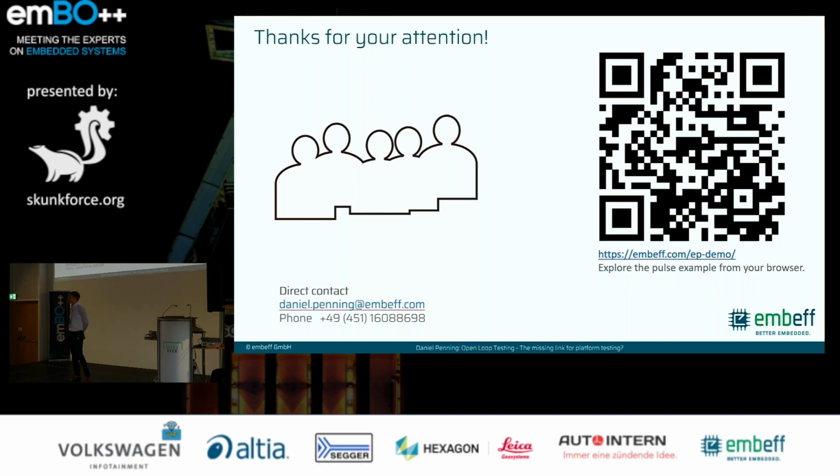What sort of device do you use within the module to analyze and interact with the pins on the microcontroller? So what device we do use? It's an FPGA. So this allows us to dynamically route to all the pins. So a typical microcontroller has like 144 pins. And this FPGA allows us to access all these pins, for example, for GPIO, and then the next test case, configure something different, like using CAN or something, and also route it out to the logic analyzer. We have some PCB there on our booth. You might take a look.